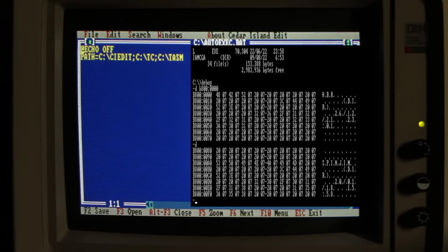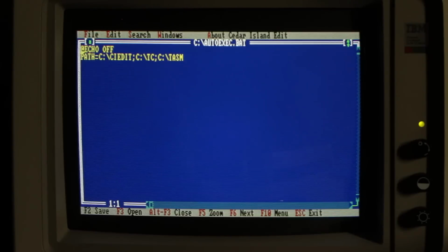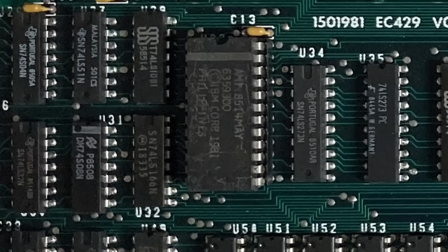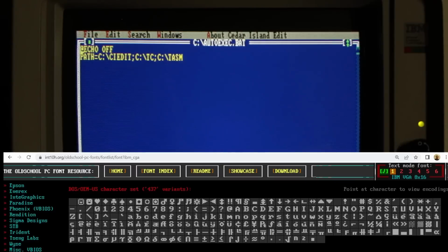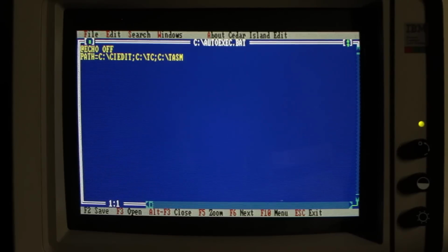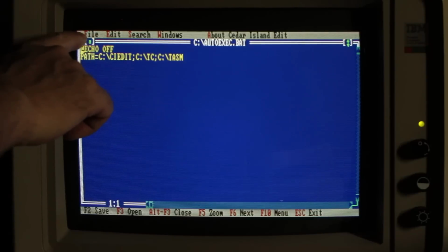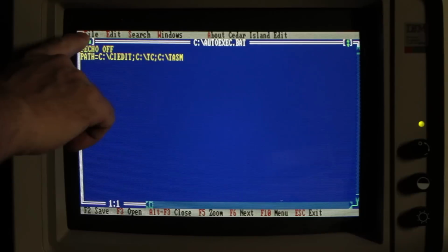And of course these ASCII codes don't tell the CGA card which pixels to display, just which character to display. The pixel information comes from another chip called the character ROM, which, if you like, has little pictures of all of the characters in it, and with all the pixel information that the CGA card should display for that character. Now, of course, the monitor doesn't display all the scan lines of the F, then move on and do all the scan lines of the I, and so on.